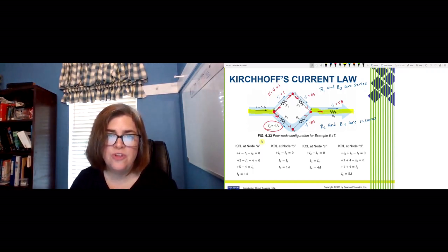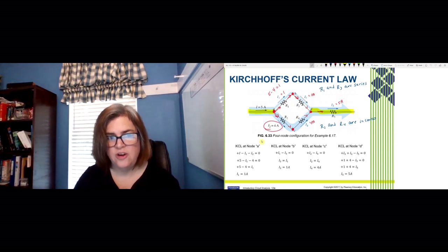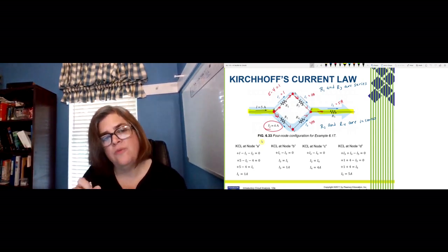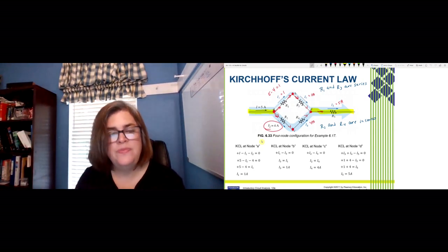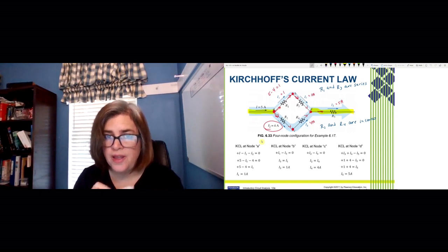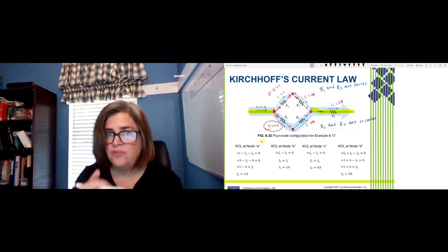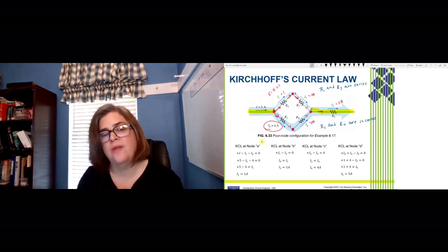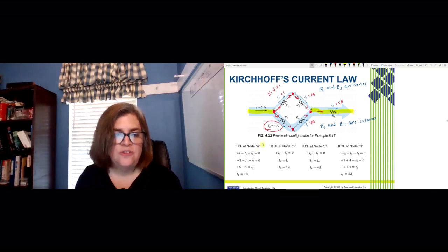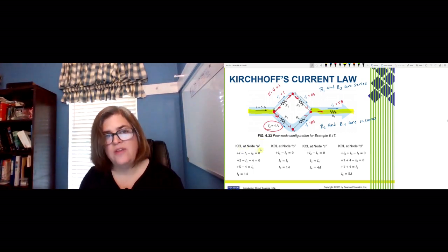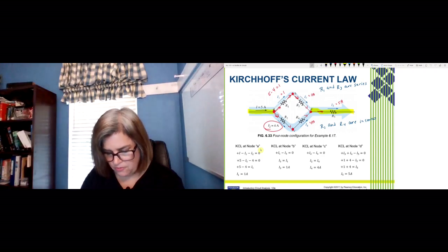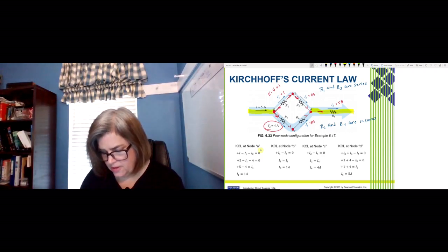And if you notice, if you're looking for parallel combinations here, if we combined R1 and R3 by adding them together, and we combined R2 and R4 by adding them together, we would have 2 parallel resistors there as well, but we'll get more into that later. So writing our KCL equations, that's what we have here. So let me get rid of what we've done up here. The equations are going to show us exactly the same thing.